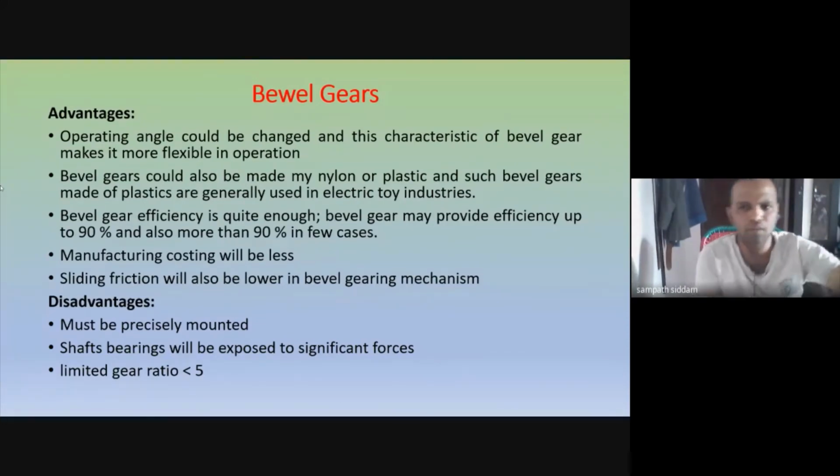Usually in the differential which you have in an automobile, we generally go with different kinds of gears, helical as well as bevel gears. In between, the smaller gears of your differential are nothing but bevel gears. What is a differential? A differential is used in an automobile at the rear end, where you want to transmit your power equally to the two axles of your wheels.